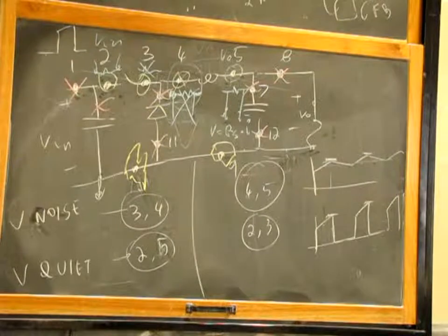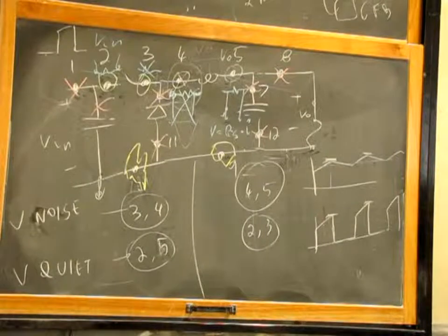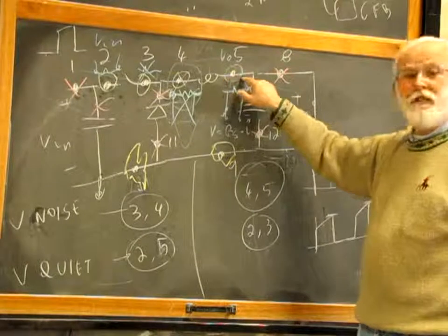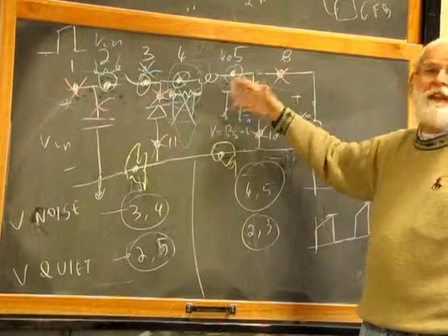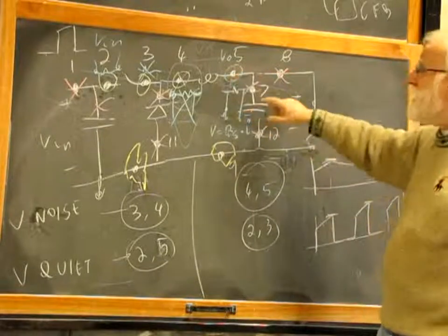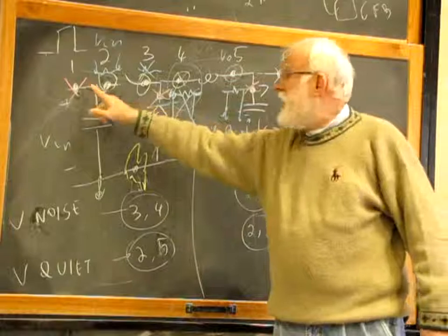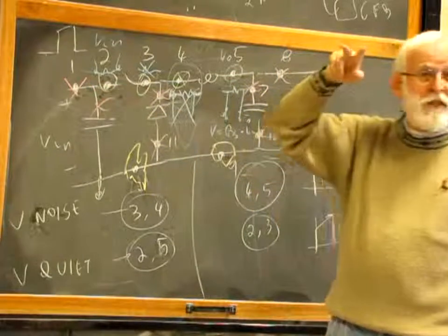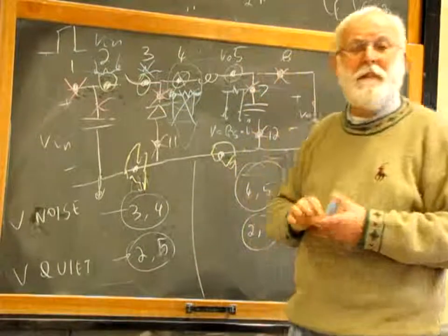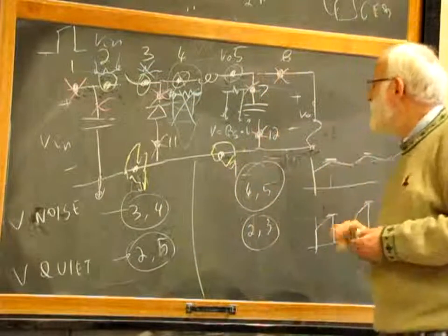In many cases, with integrated ICs that have everything inside except the sensing resistor, the sensing resistor is placed over here, on the series inductor. You dissipate more power, that's okay, but inside the IC you can measure it easily. If your IC is supplied by this input voltage and you want to measure a small difference at the same voltage as the input, it could be difficult. It can be done, but it's not so straightforward. Here it's easier.